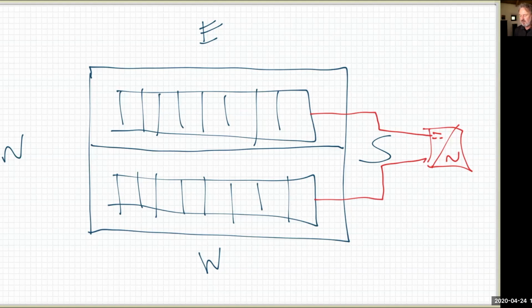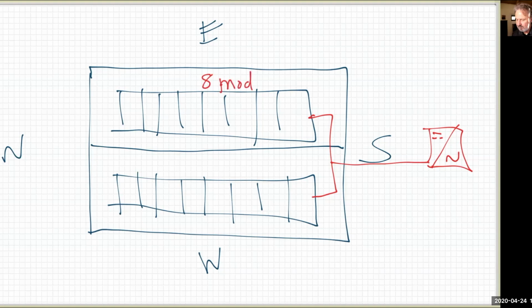But there's another option, and this option is allowed under 5033, and surprisingly it works. And I'll just draw that one. If we join these 2 together, so we've now paralleled, whether it's on the roof or down at the inverter, it doesn't matter. We've paralleled 2 strings, but the rule is they must be the same number. So we've got 8 modules on this side.